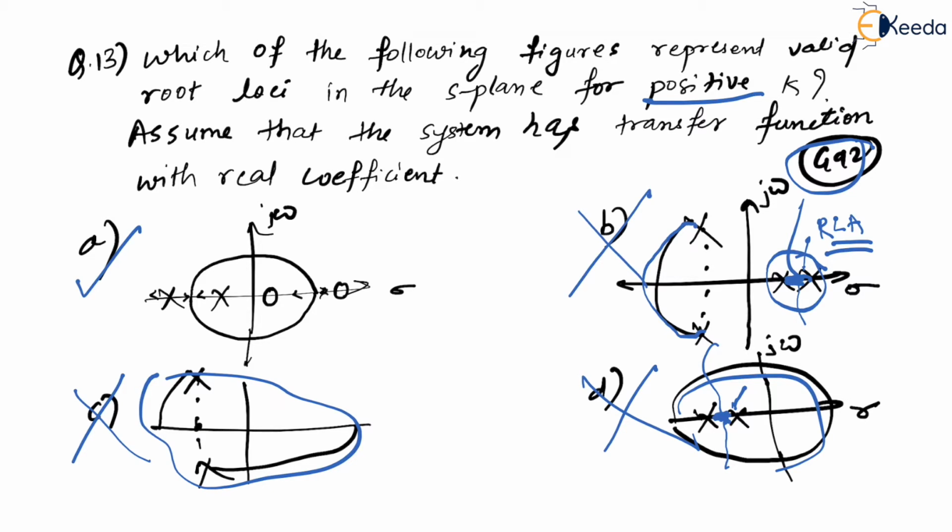Let us first verify. It has to be right, but still we will verify. See, is it root locus area? Yes, it is a root locus area, which means definitely there is a break-in point here. There are two poles, so the two poles have to terminate at two zeros. Two open loop poles which are there, they will have to terminate at two open loop zeros, correct?